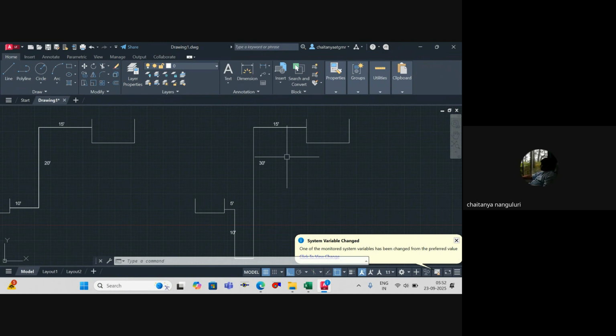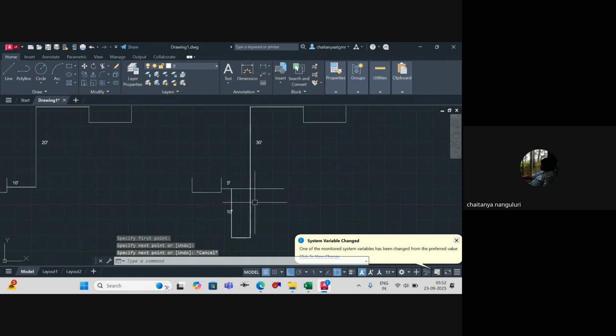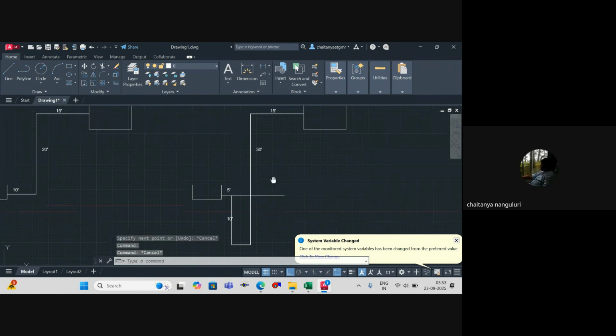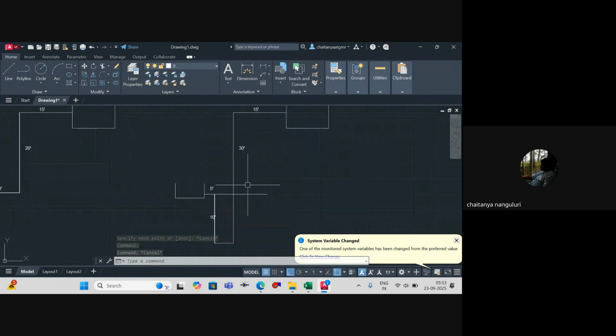Because of gravity, don't you think the water will automatically come up to this level inside the pipeline? Though you have a U-bend, because of gravity, don't you think your water will try to reach equilibrium? So your actual thing is only 20 feet, which is 30 feet minus 10, to calculate the static head. Understood? Okay. Am I clear?